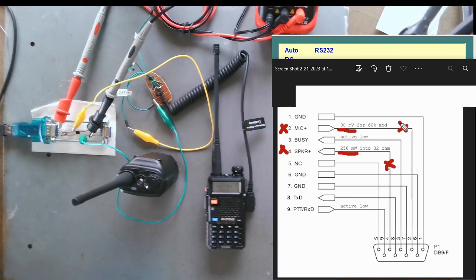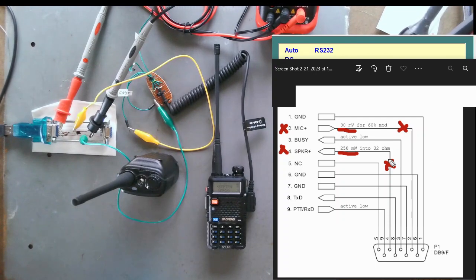We're going to need that because you may have to turn the volume down, whether it's the speaker coming out, because it may be too high for the software that you're trying to run it with, whether it's Zello or some other type of software. And obviously there's no volume control on the repeater itself. There's some volume control on the computer, but that may not be enough. So that's why we have to add that. We're going to need to come up with what values to add there, but that's not going to be until we do the audio part of this video series.